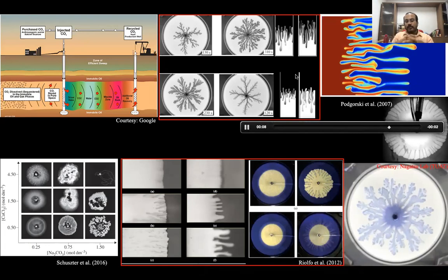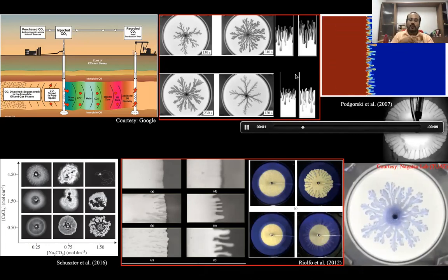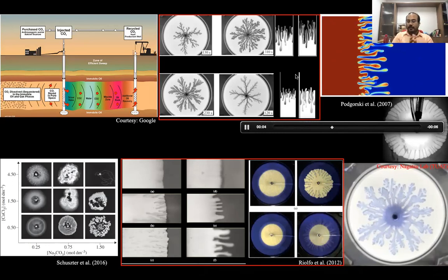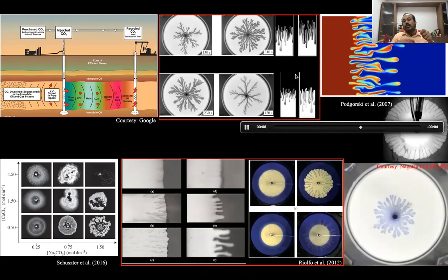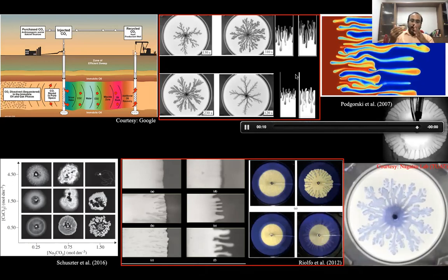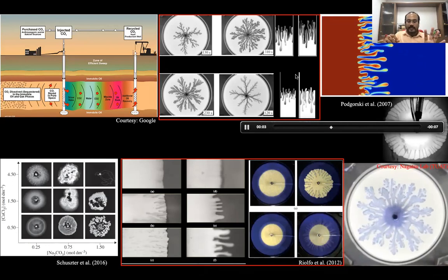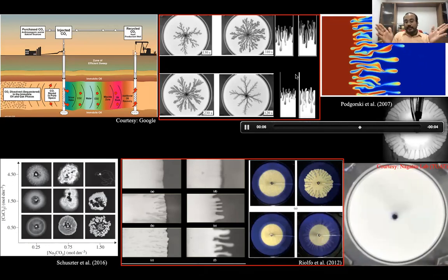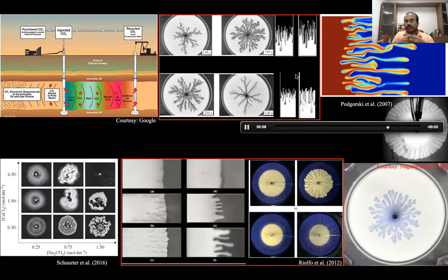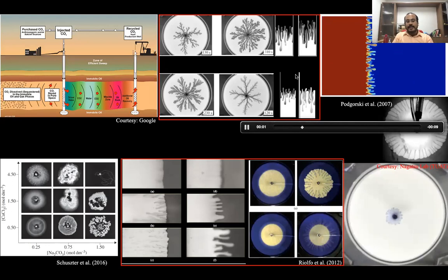From the fundamentals of fluid dynamics, we know the radial flow behaves differently compared to rectilinear flow. For example, for a radial source flow, we know that the velocity decays as one over the distance from the source where the fluid is injected. Whereas for the rectilinear flow, nothing like that happens; the flow velocity does not decay. So there is a fundamental difference between the rectilinear and radial flow.